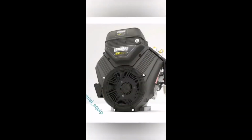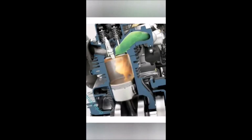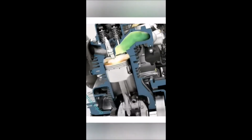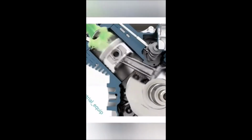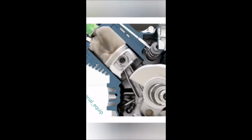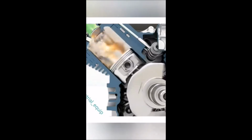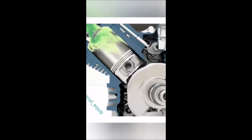Variable ignition timing advance. Modern electronic fuel injection systems often control more than just fuel delivery. The spark events are also controlled by the ECM. Depending upon engine speed and engine load, the spark event may be required to occur much sooner or later in relation to the piston traveling toward top dead center. Variable spark advance is a tool used to always keep the engine producing maximum leverage on the connecting rod and crankshaft, thus making the most torque and efficiency possible.